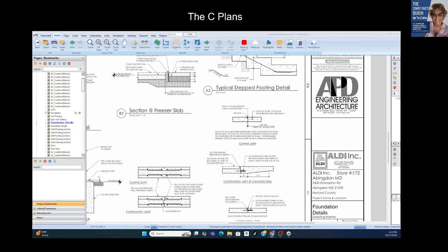And then we have the footing, the continuous footing that goes around, right? But then the building sits on stem walls. So we have the foundation footing, and then we build, like we saw in some of the section views, that wall we saw. And then the building structural walls are built on the stem wall. Okay, so that's a spread footing.